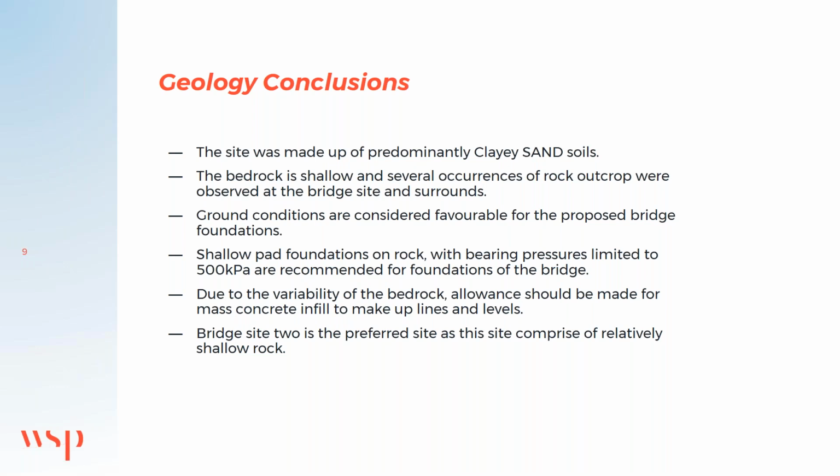The bedrock was also shallow enough since we saw some rock outcrops appearing on the river. The ground conditions of the chosen site, and I'll be taking you through the process of choosing the site, the ground conditions of the proposed site were actually favorable for pad footings on a 500 kPa bearing pressure capacity.